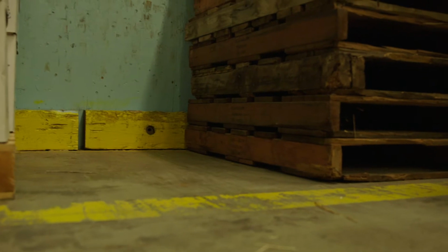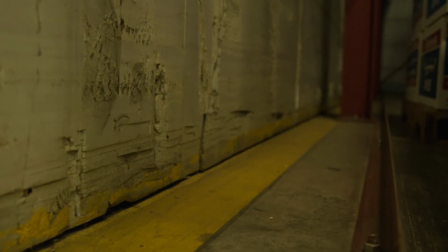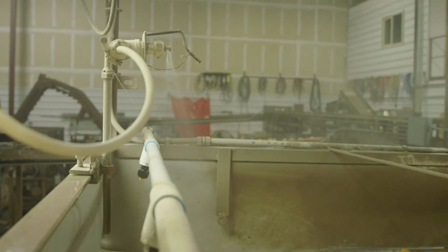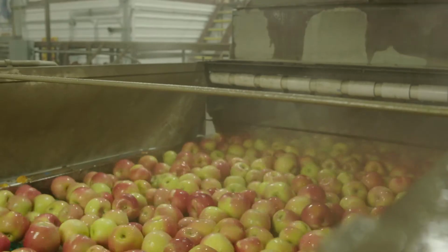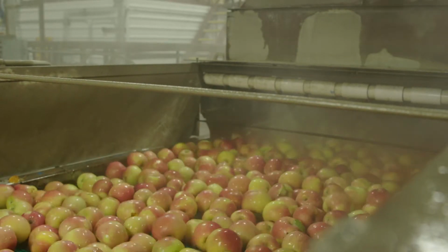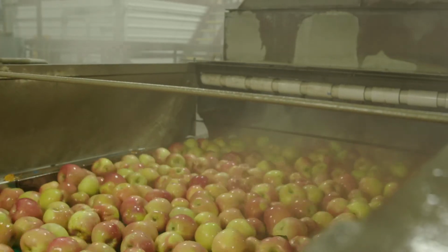Many of these places are hard to reach and oftentimes overlooked because we don't think they could contribute to contamination of produce. For example, the interior surface of spray nozzles used to rinse off produce as it passes on a belt. If these nozzles are not cleaned regularly, a biofilm layer could build up and potentially contaminate the water and eventually slough off onto the produce. Hard water or organic material may clog the nozzles, causing water to drip or drain down the sides of equipment and subsequently onto produce or spread contamination.